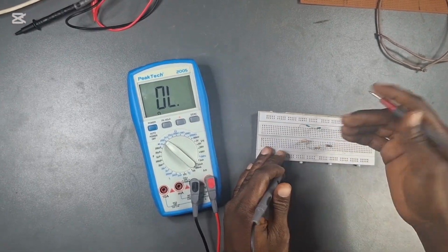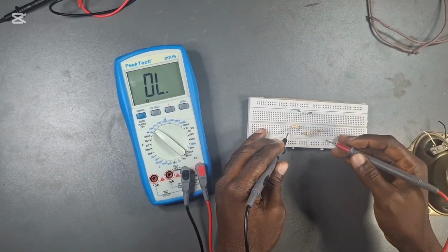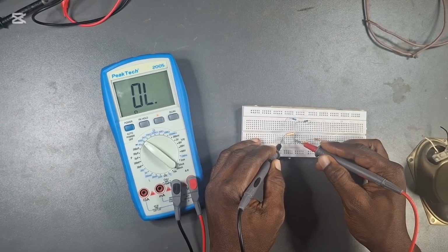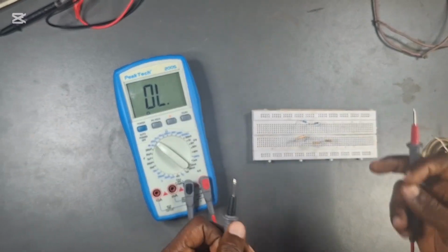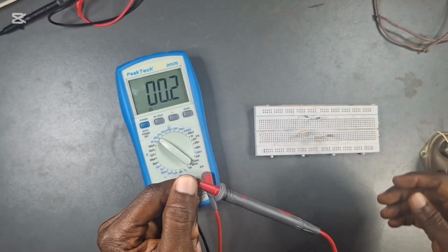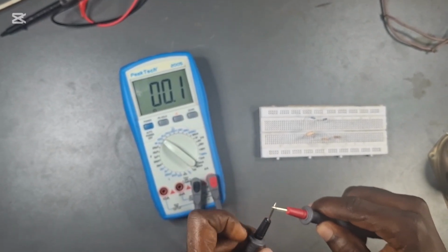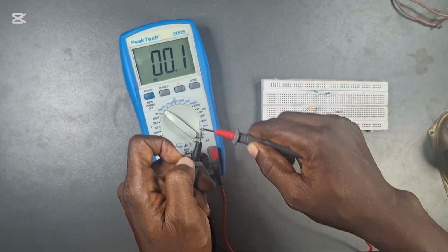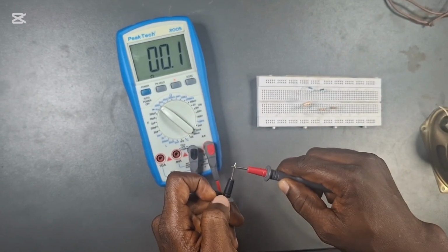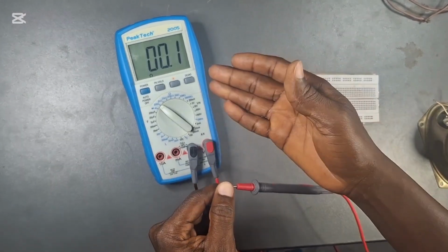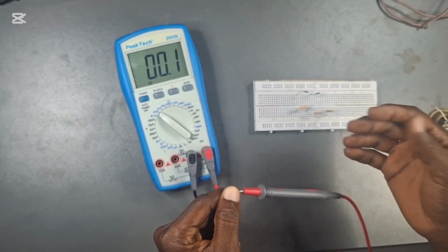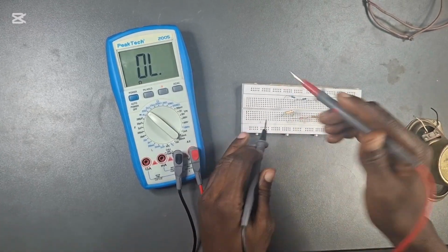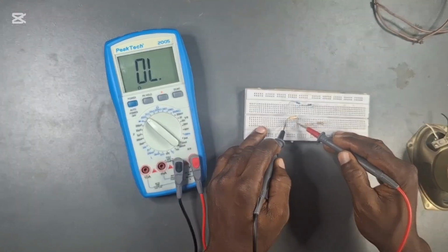So these are all resistors. We are going to measure their resistances. So let's take it one after the other. So let's measure this first. All right, so there is no reading, but first of all, you need to make sure that you shorten the probes of the terminal. The short leads are connected together like this. And also, the reading should display ideally 0 ohms. But now we can see 0.1 ohm showing, but that is not bad. So let's get started. So we take our measurement.